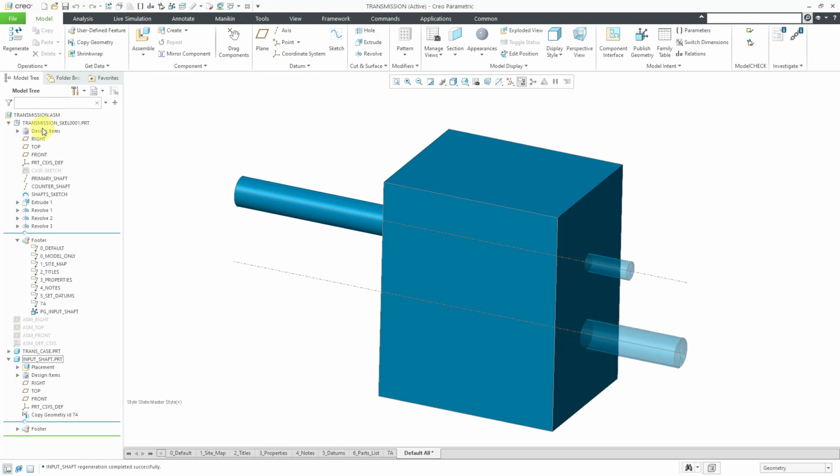What you're going to do is create that special kind of part model that you can filter out automatically from your bills of material. Also, if you have any solid geometry in here, it won't contribute to your mass properties, but you have this 3D geometry as a reference for making your additional components. And because we use those data sharing features, we can control the dependence between the skeleton and the target parts. And also, if we make changes to the skeletons, we can have them control the geometry in the individual parts as well. So this is how you do it on the Creo Parametric side.